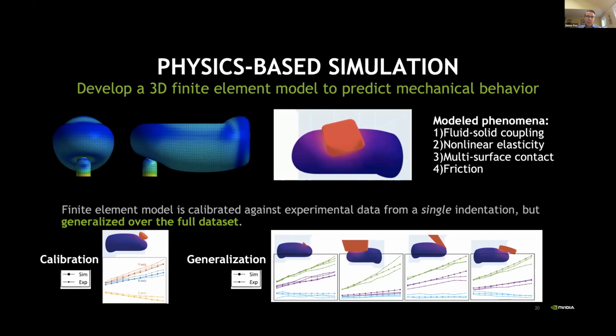We feed that information into the finite element method to predict how the BioTac would deform or react to this indentation process. Through the finite element method, we then also predict the overall resulting force. And that resulting force is then compared to the force that you measured with the force torque sensor. Okay, and he got a very good matching between those.